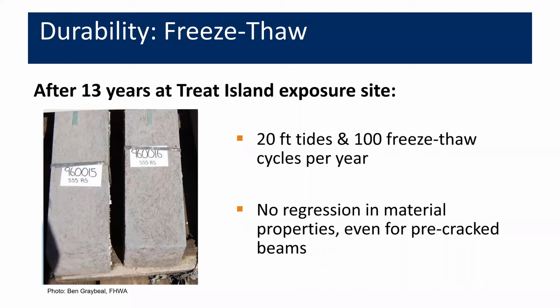And again, I mentioned earlier that we don't include air entrainment typically in UHPCs, but they do have this ability to resist the freeze-thaw distress as a result of its high strength and the low porosity that keeps the moisture from moving through the material.